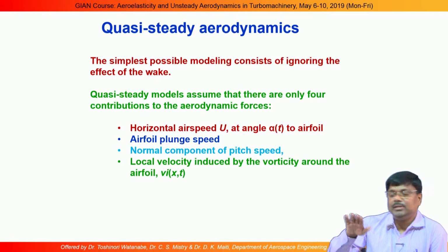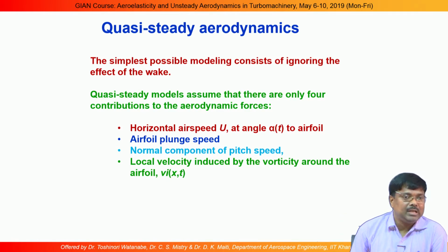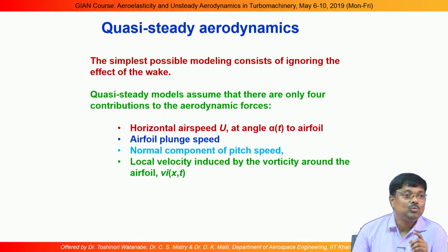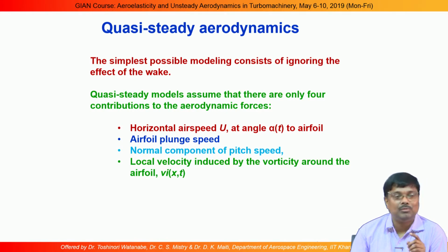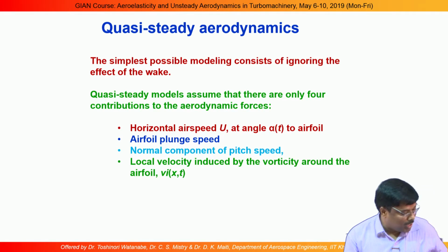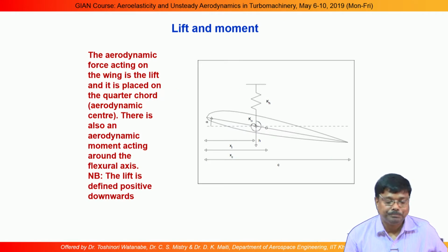You see, when it is oscillating in a steady aerodynamic load, what we have considered is that the aerodynamic control point is the quarter chord point. But when it is oscillating like this, the control point has changed to the 3/4 chord point towards the leading edge. So, due to this oscillation, there will be some additional lift force acting. I will show you how it has been calculated.